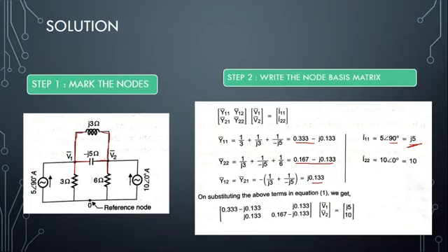Why this 90 is j, maybe that too I can say. Angle of 90 is nothing but cos 90 plus j sin 90. Right. So cos 90 value is 0, sin 90 is 1. So when you write cos 90 degree plus j sin 90 degree, cos 90 becomes totally 0, sin 90 becomes 1. So only this j term remains for us. That is why we say angle of 90 is nothing but just j alone. The real term vanishes for us.